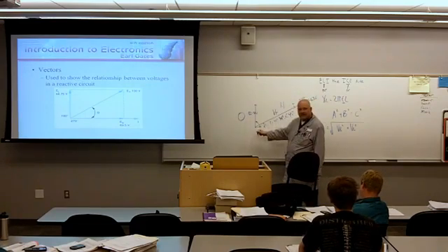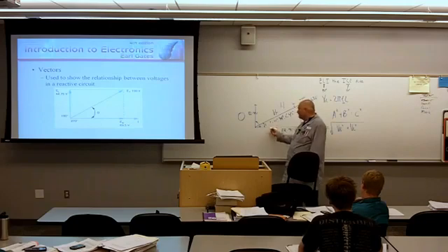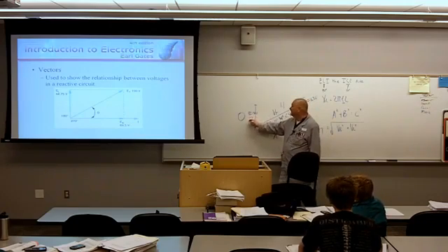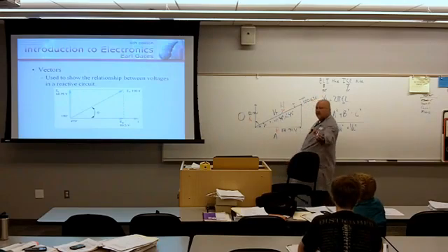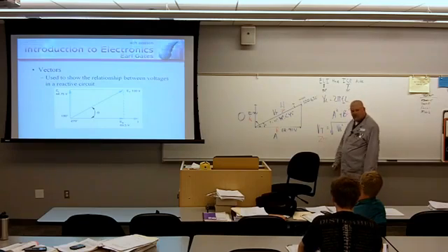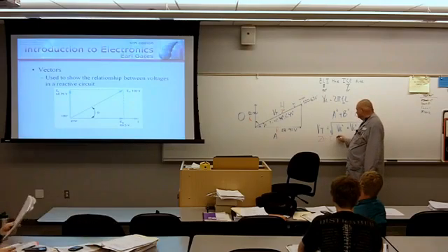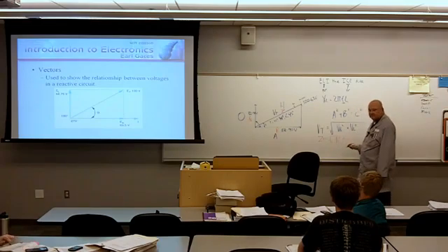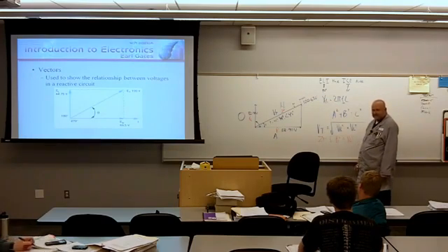Here you're looking at, if I'm looking at R on my adjacent side, what am I looking at on my opposite side? I'm going to compare R to X what? XL. Very good. And what's the combination of resistance and reactance inside a circuit? Z. So if you want the formula for Z, Z total, if you like, is going to be equal to the square root of R squared plus X sub L squared. If you don't have the value of X sub L, you need to get it and execute this formula.